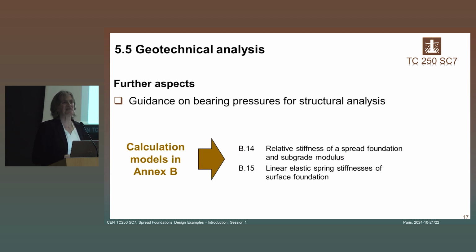Further aspects are also dealt with there, for example, guidance on bearing pressures for structural analysis, and there are some additional calculation models in Annex B on the definitions of the stiffness values for subgrade modulus. So overall, you can see there are a lot of additional calculation models in the Annex, 16 different annexes you have in the Annex B.